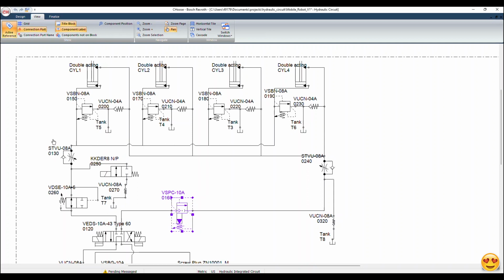So it's really important that the whole platform is lifted up from the four sides simultaneously with the same velocity and flow rate. So this one regulates the speed, how fast the platform will be lifted up. So it plays a very important role.